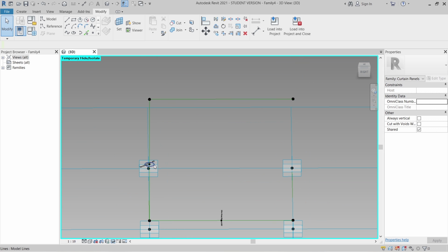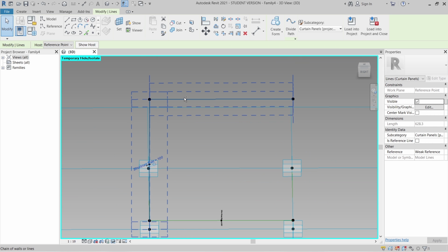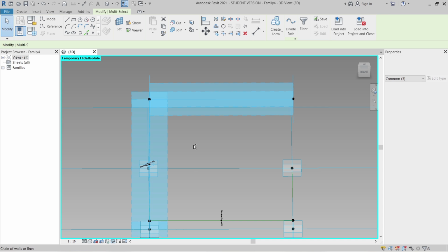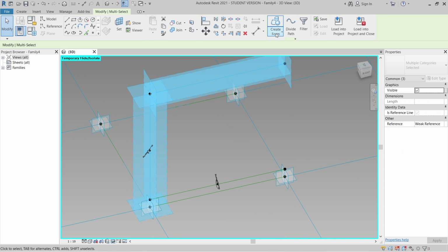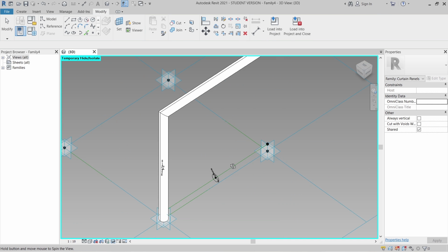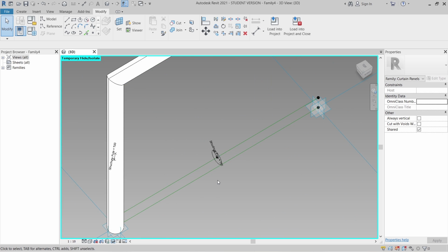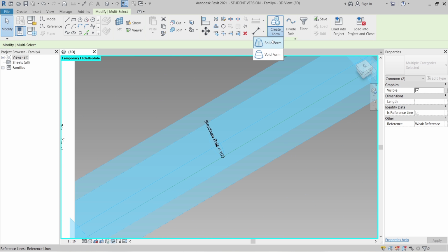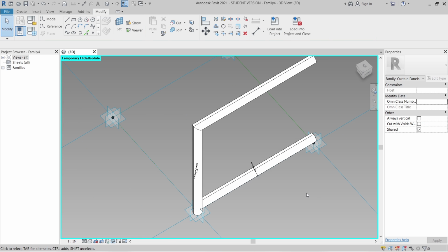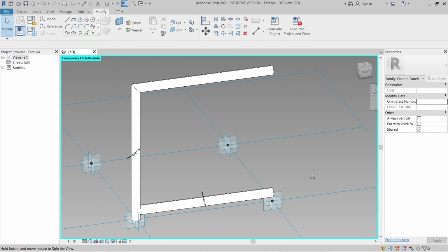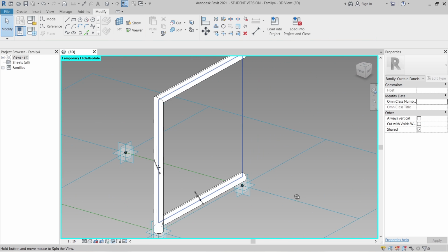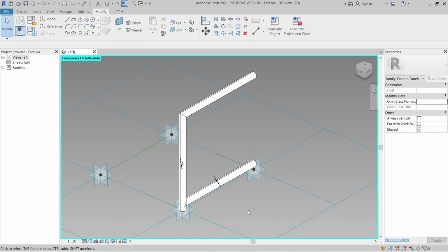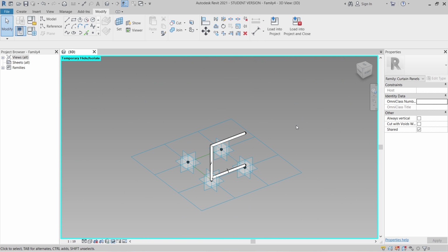It's time to create our pole shape. I can select my circle there, select my reference plane here also, then simply create form and solid form. As you can see, we got our pole already, and there I'm going to create our pole as well. Okay, perfect. The reason I never create pole there, later on you will know the reason. And now I want to assign for material as well.